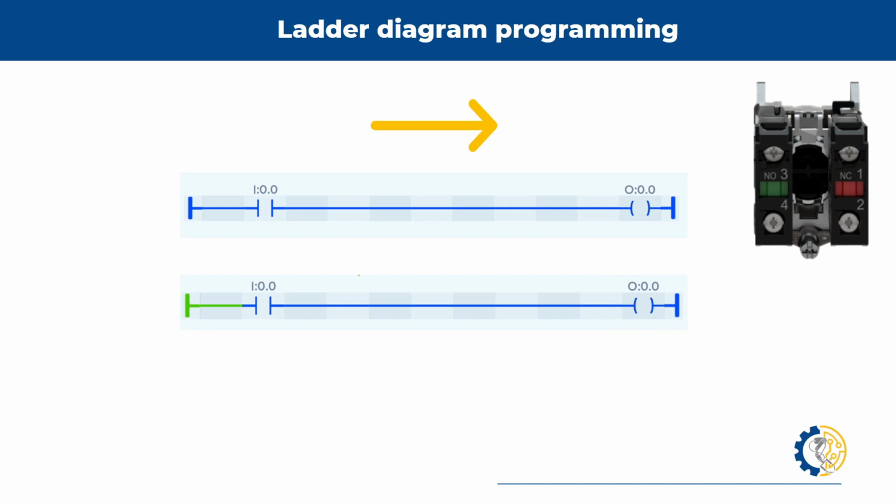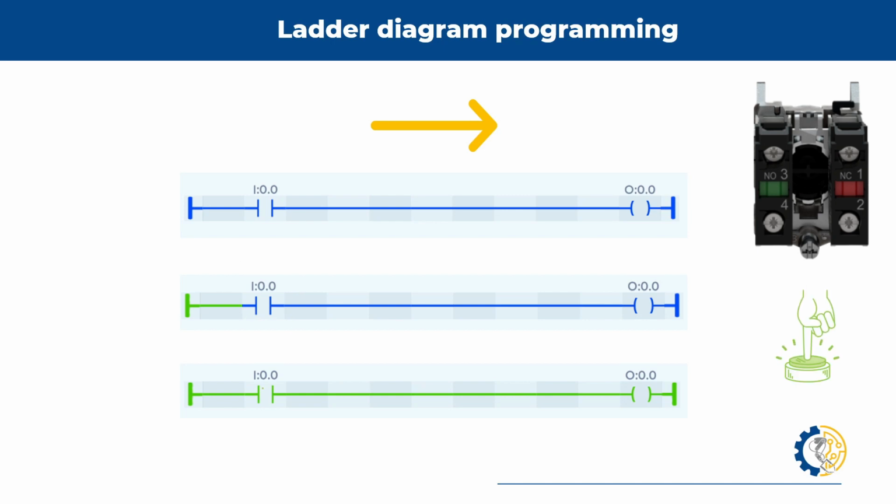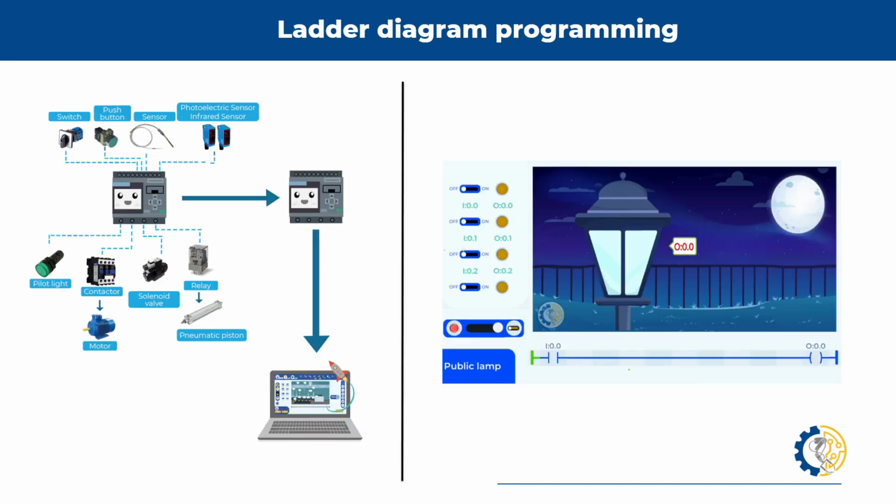Step number 3. So step 0 is off. In step 1, we already prepared our PLC. We're ready to look at the signal. And now we can press our green button, which is going to be closed. So therefore, we're finally going to allow an input to power on my output. So we read from left to right. Remember, left to right, top to bottom.